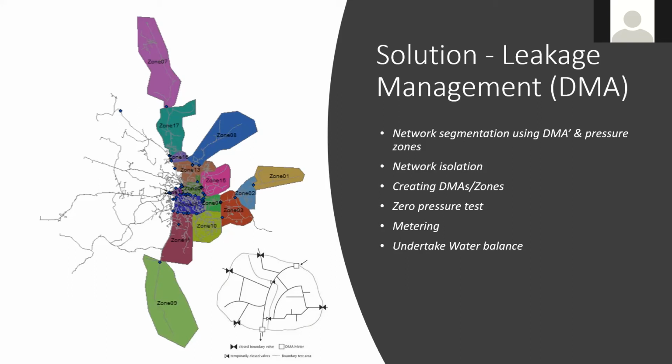Clearly, we couldn't have done this in the absence of a GIS, because to achieve this, we need to have a GIS system in place that tells us where these pipes are to start with, where the valves are within the network, where we have all the necessary appurtenances, the meters, all of those things. We need to have them first so we could build on it.